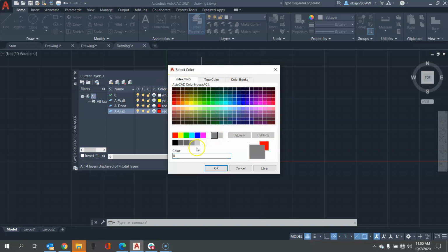Now, when you see the options, you will have 255 color options. The way I set up printing is connected to the layer color. I always draw objects in the layer with the layer color. If I need a different color, I create a new layer, and I set up how the whole layer is going to be plotted, meaning how it's going to come out on paper,